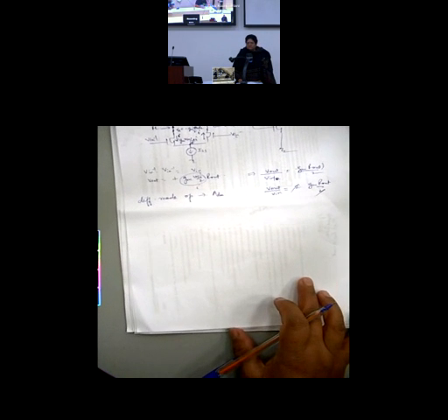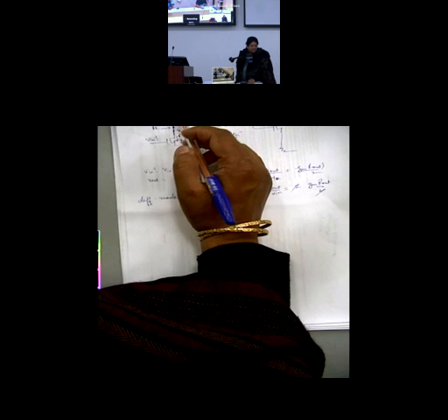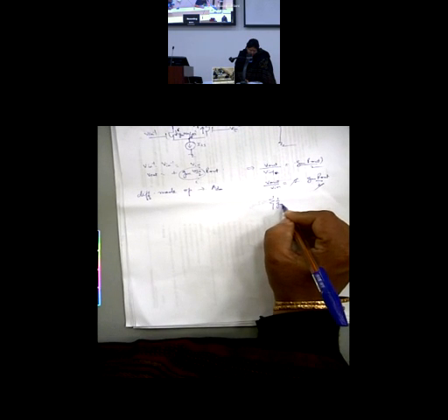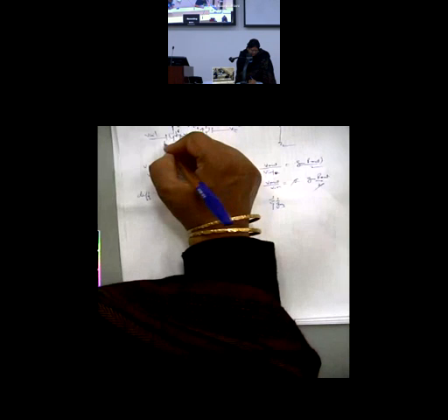So we have something called ADM. Now I need to look at A difference mode, again at low frequency. A difference mode is very simple. Now I can draw an AC model right here. So this would be replaced by 1 by gm. So I am redrawing. This is 1 by gm3. This is M3, say this is M1 and this is M2.